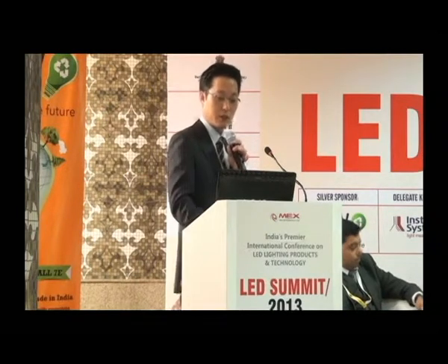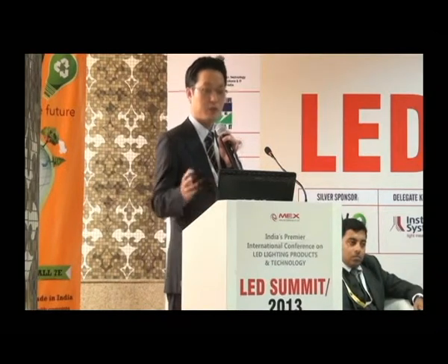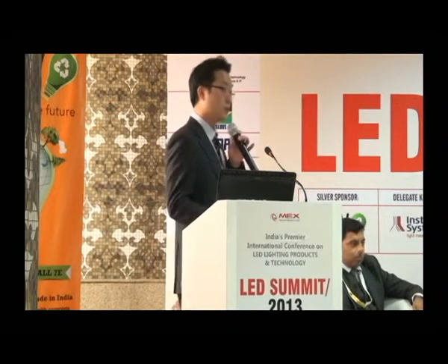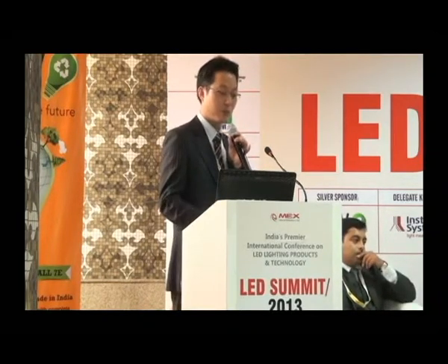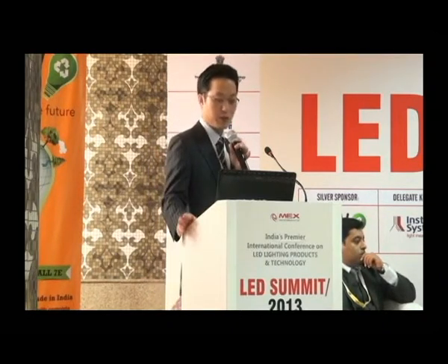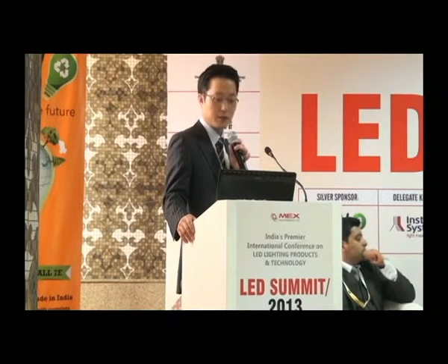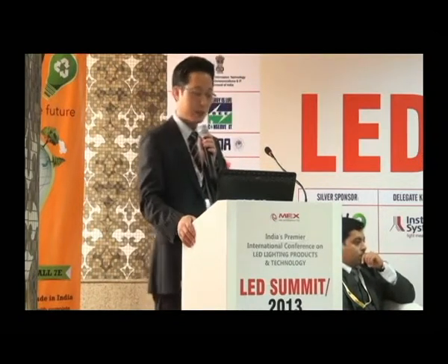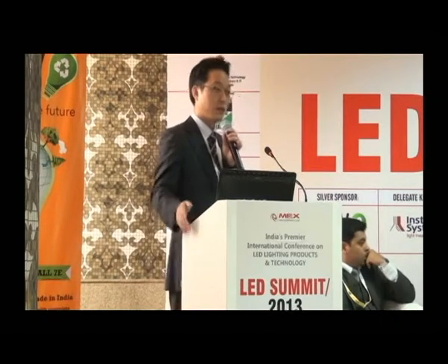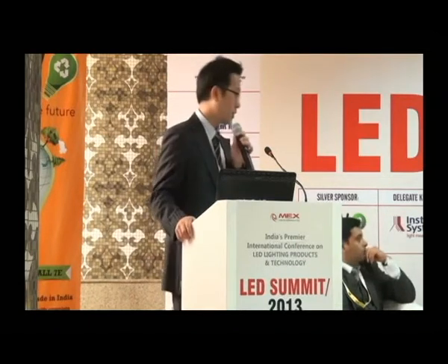A71 is designed for this kind of multi-chip LED encapsulation. A72 is designed for the single chip solution, which is mainly used for backlight unit applications. And A68 is also designed for the single chip solution, but the special thing about this grade is that it is mixed with phosphor. Nowadays every LED customer is mixing phosphor material to make white light.